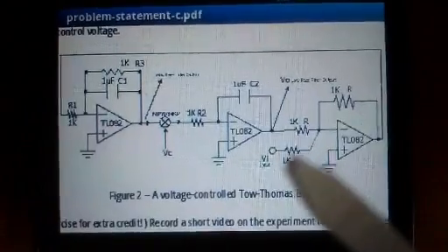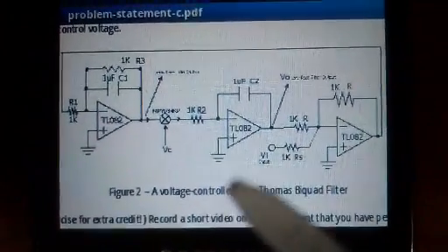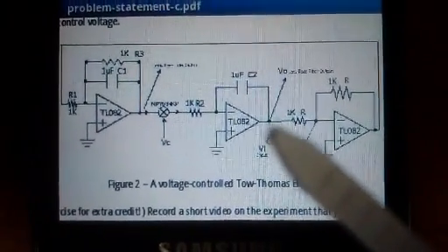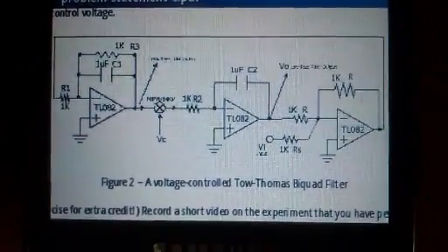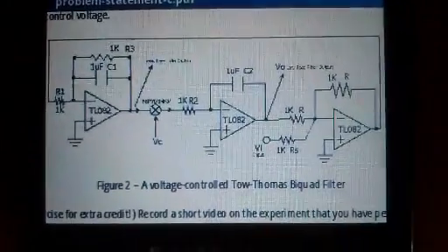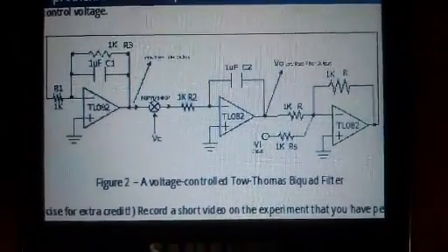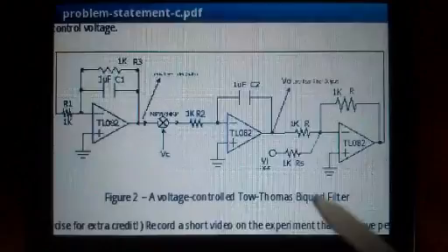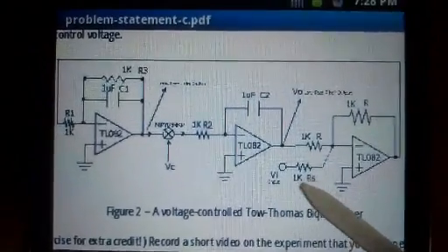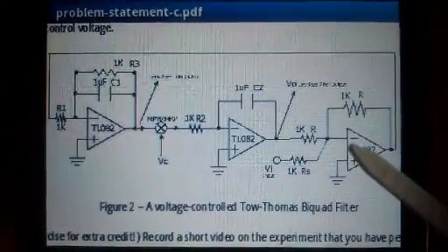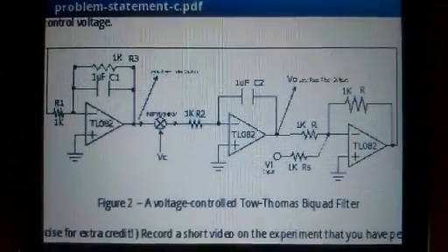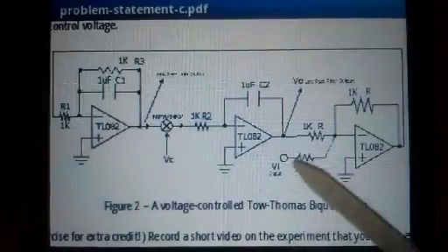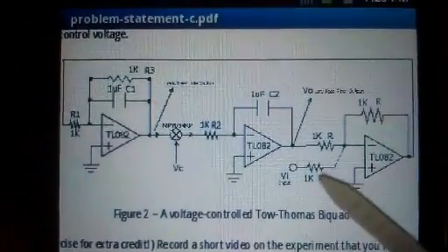So it's this node, and the response from this node to this node is essentially low pass, and so this acts as a second order low pass filter. One of the problems we faced while designing this on the board was this resistor, because each of the op-amps had only 2 resistors connected to the input terminal and negative input terminal, and to tap this resistor out we had to tap out the resistor from another op-amp.